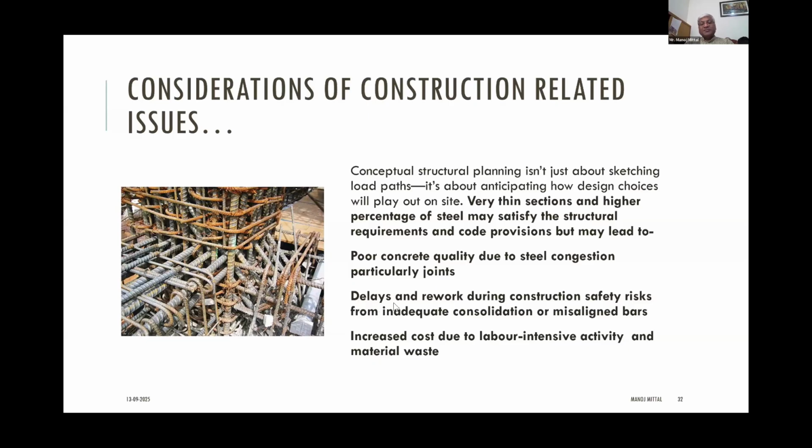It may lead to delays and rework during construction. It may lead to honeycombing. It may lead to so many other things, and increased cost due to labor-intensive activity and material, because placing reinforcement like this is a really very difficult task. So we need to consider this aspect also while deciding structural element sizes during the concept planning stage.